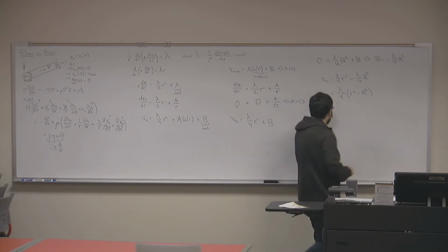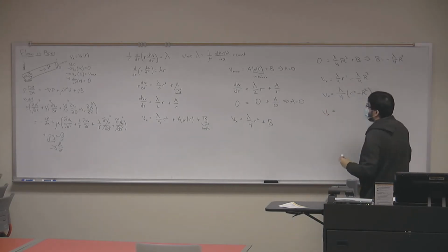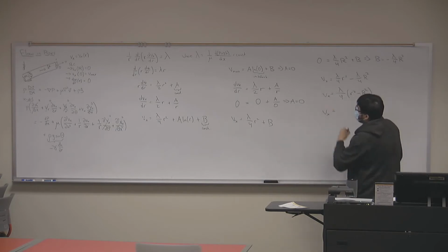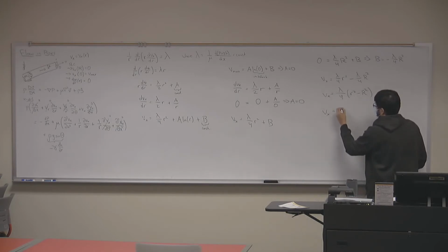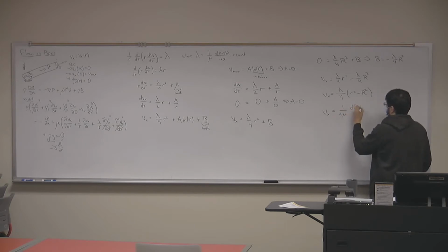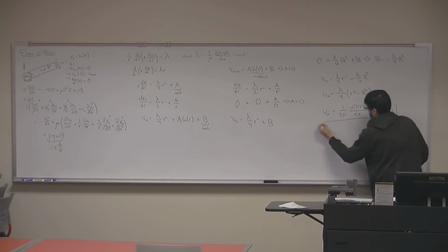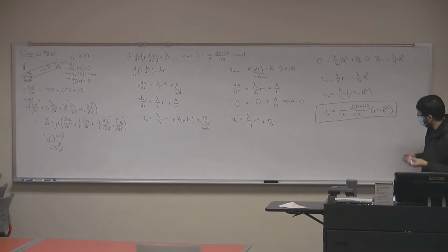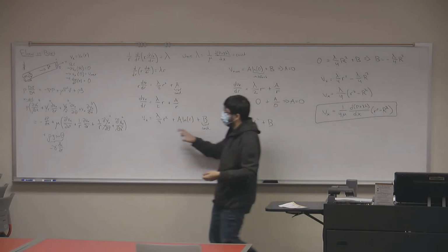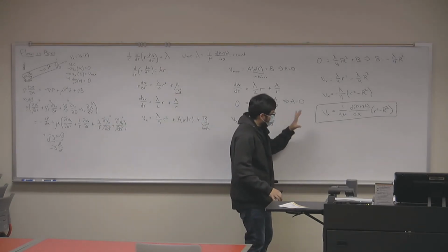Let's plug in that value for lambda so we can get the final, the latest and greatest, equation. So lambda is 1 over mu times the pressure and gravity gradients. So I'm just going to say 1 over 4 times mu times d of (p plus gamma h) over dx. And all this multiplied by r squared minus the radius of the pipe squared. And we get a pretty nice, easy to use equation, pretty much starting from Navier-Stokes. And yeah, it's something pretty solvable.